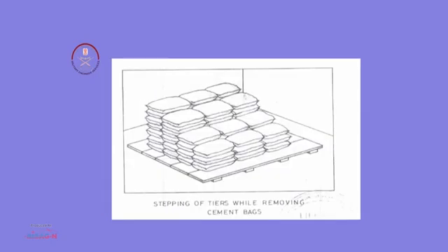And then when we take out the cement, we should prefer to take it out in steps. Instead of taking all the bags from one stack, we should take more from the first, a little less from the second, a little less from the third, likewise, so that toppling of the stack may not happen.